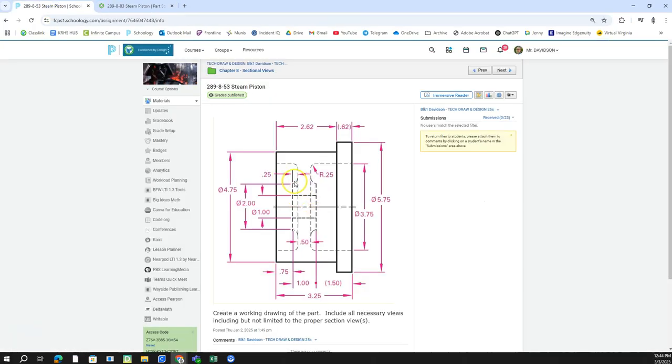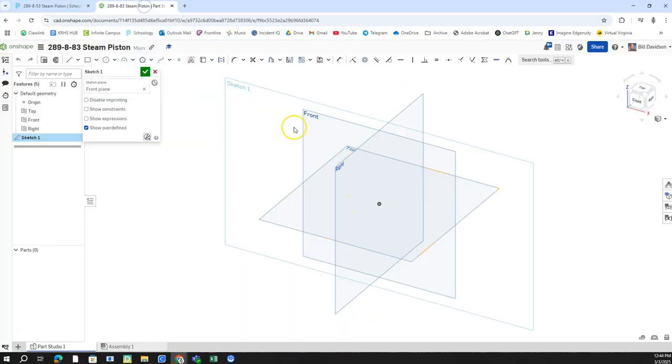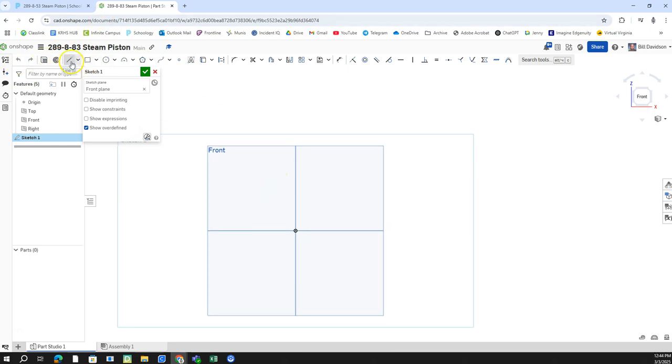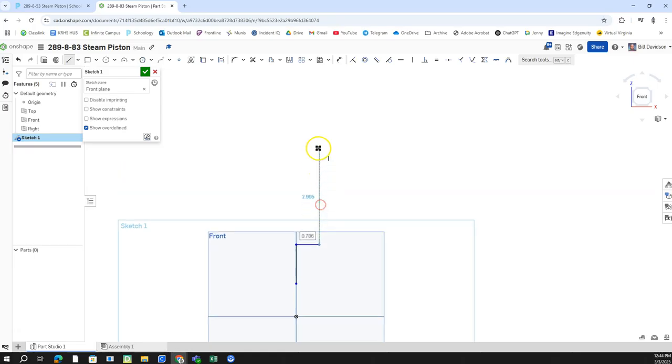When I go in here, I'm going to click New Sketch, and I'm going to think of that shape that I have right there. I'm going to sketch that first, and I've got to attach it to the origin point. So right click, confirm that right there, and I'm going to start by clicking somewhere right here. I'll go up to about there, over to here, maybe go up to here, out this way a little bit, trying to remember what that shape looked like.